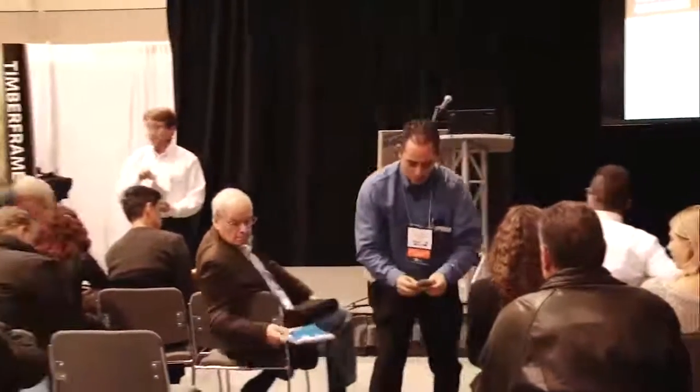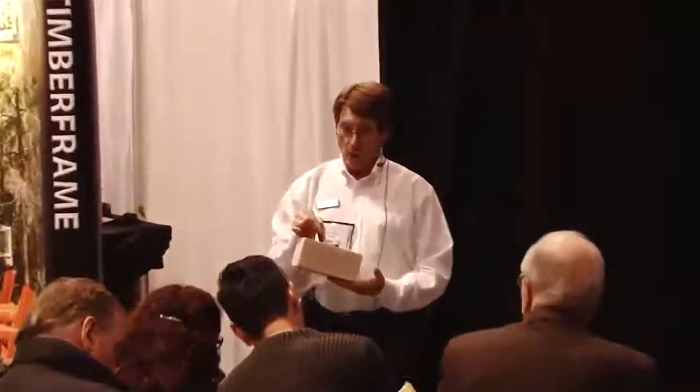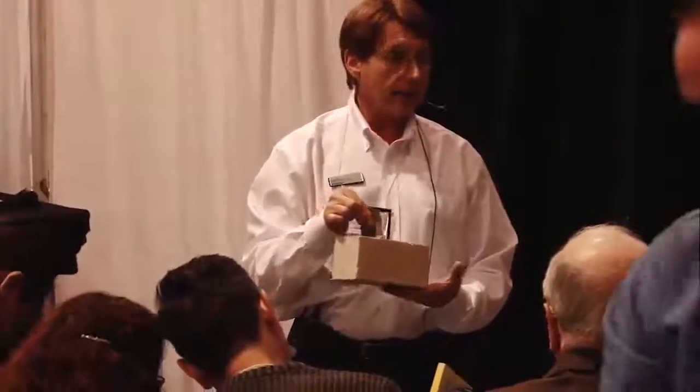With these types of products, without the use of a primer, we're able to take these membranes and stick them to concrete, stick them to dense glass gold, stick them to a number of substrates without the aid or use of a primer. When we take a look at SBS modified membranes, everybody can clearly see that there's an advantage that if a mechanical fastener had to go through the membrane, it's the material on the back that will seal around the shank of the fastener and cause it to seal.